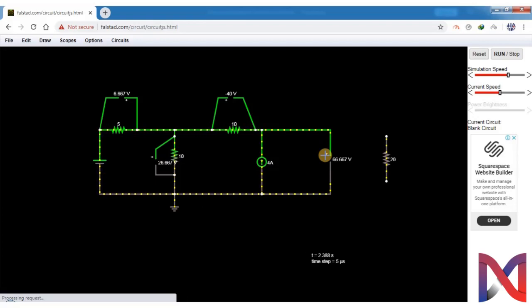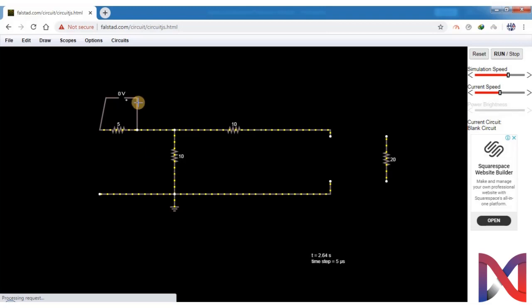Our next step was to calculate or find the Thevenin resistance. For that we need to cut or disconnect the voltage source, as well as open the current source. For simplification, we will delete all of the voltage meters, so that we have no extra components and wires in our circuit. Now our circuit is simple.